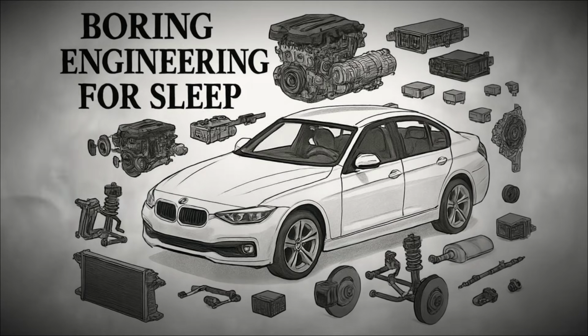Brake fluid is a key part of this system, and it must withstand high temperatures without boiling, since boiling would create vapor bubbles that compress instead of transmitting pressure. For this reason, brake fluid requires periodic replacement to maintain safety. Modern braking systems also incorporate additional technologies.